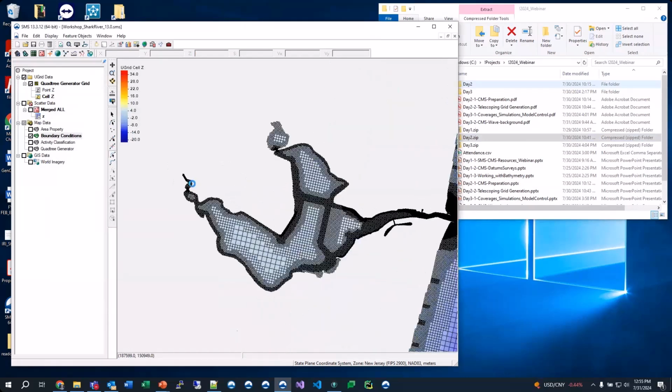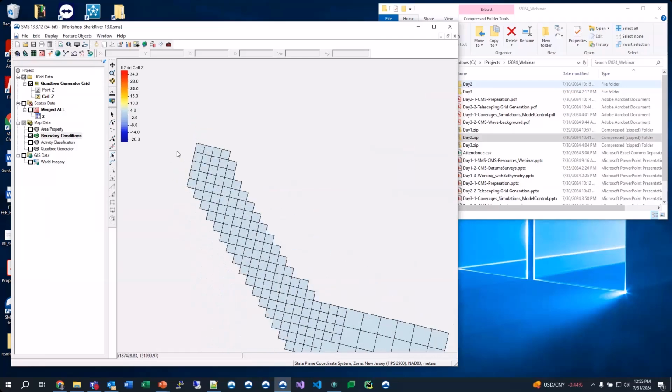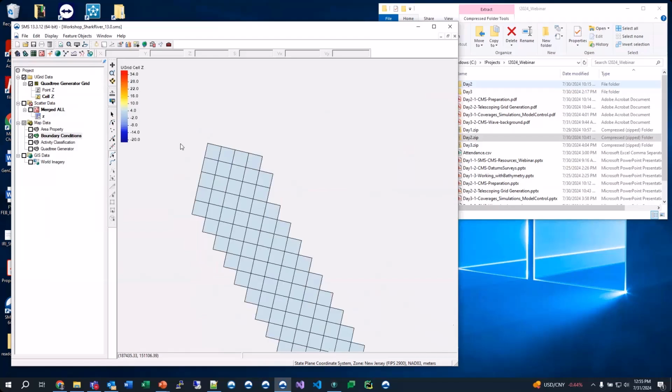Quickly, I'm going to go to the river section here and give a little bit of a demonstration of how to do forcing in this area. There are a couple of things that you want to make sure you do or not do in this case. When we're doing rivers, we are providing an arc along a certain row or column. You can't have an angle with a river flow, so make sure you don't have any kind of a corner. It's got to be either on this side or this side because of how we have the grid set up. I'll choose this side right now.